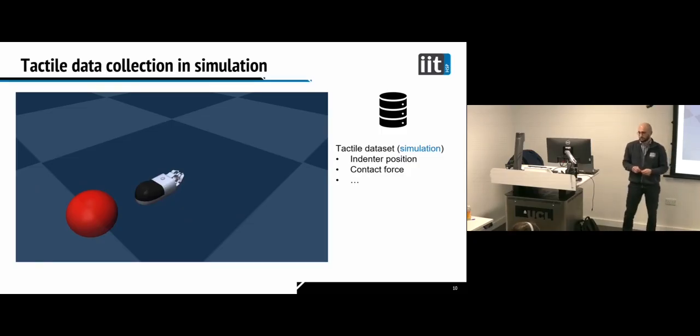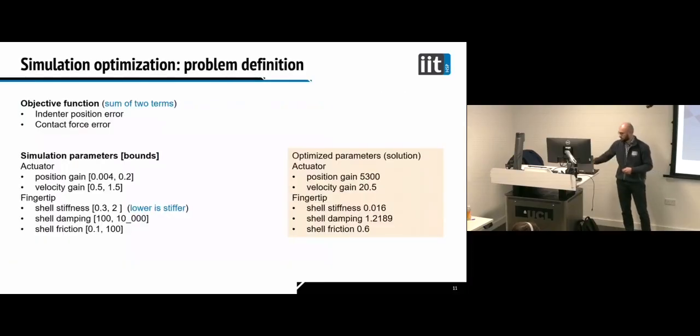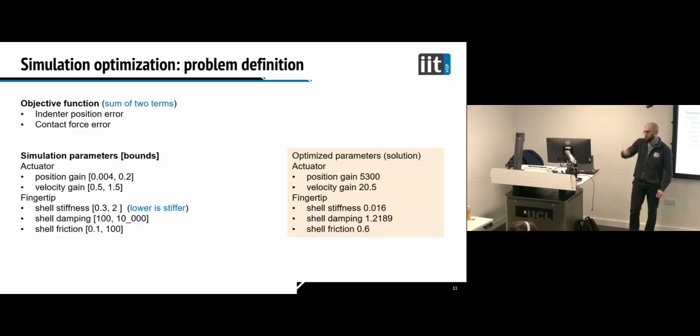And the other 3 parameters, which are the stiffness. So this will be the soft material, kind of trying to estimate the material properties of the real one. Yes, MuJoCo doesn't give you so many options, but these are the common parameters, let's say. Stiffness, damping, and shear friction.